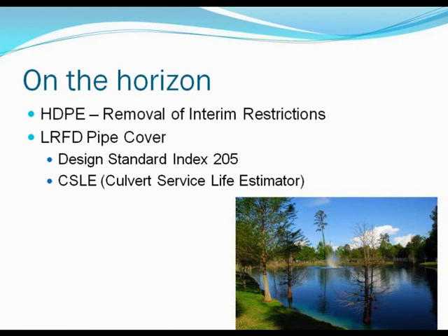The interim restrictions were having to do with under limited access right-of-way, 8-lane sections, adjacent to buildings, things like that. Polyethylene pipe Class 2 will still not be allowed in the Florida Keys due to the heat and service conditions. And so on designs coming up, as you're doing optional pipe, the only restriction on the polyethylene, other than the current cover restrictions, should be that it's not used in the Florida Keys.